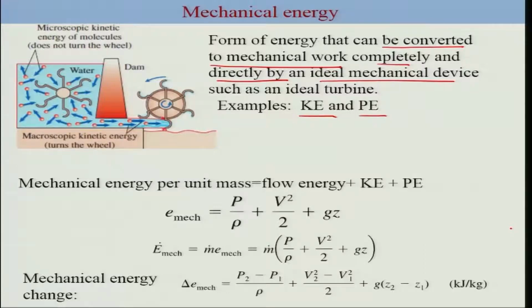The pressure, though, is not an energy, but when the pressure force acts on the fluid through a distance, it produces a certain work. This work is called flow work. For convenience, we say flow energy, and we include that as a part of the mechanical energy. So overall, we can define mechanical energy in this form.